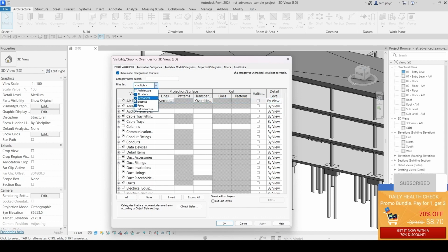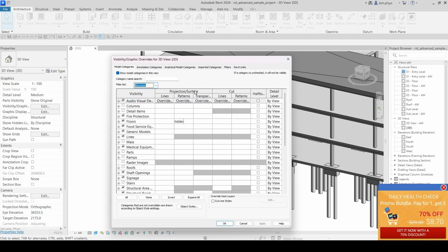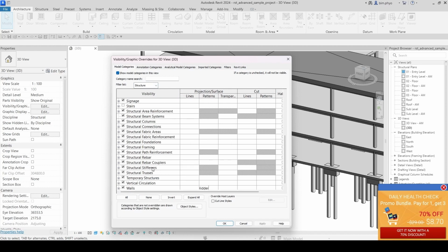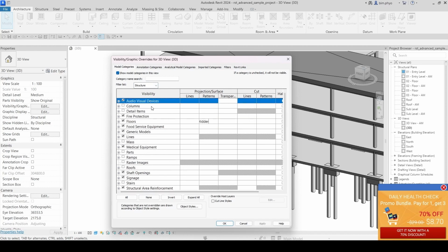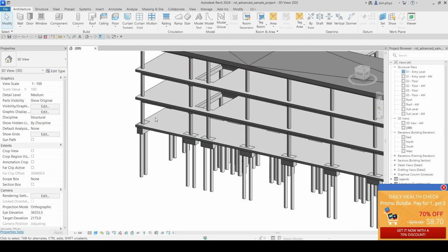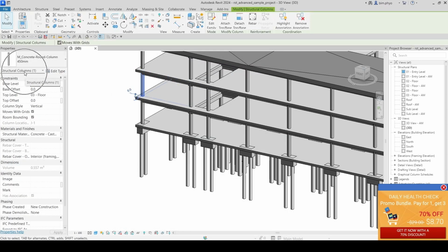Okay, I will look at only the structural elements. Those are structural elements here: stiffener, wall, or the column. For the column, this one is the architectural column. In here, that is a structural column. There are two different things. Do not be confused about it. When you see a column, don't straight away assume it is a column, it may not be the structural one. That is an architectural one. If you see structural columns, that is a structural material.